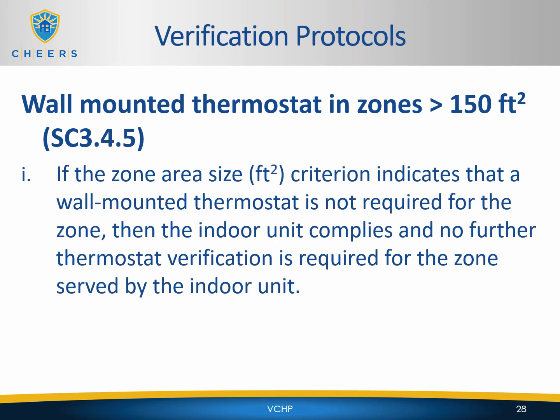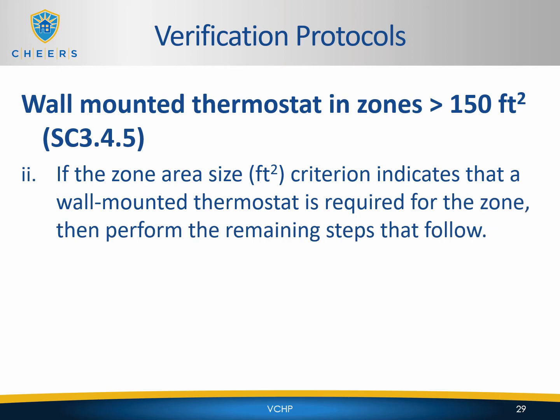If the zone area size criteria indicates that a wall-mounted thermostat is not required for the zone, then the indoor unit complies and no further thermostat verification is required for the zone served by the indoor unit. If the zone area size criteria indicates that a wall-mounted thermostat is required for the zone, then perform the remaining steps that follow.